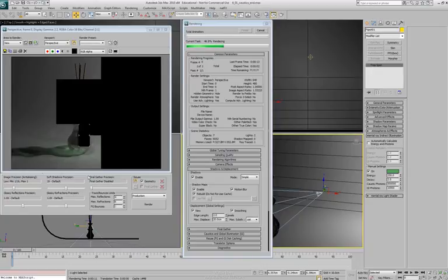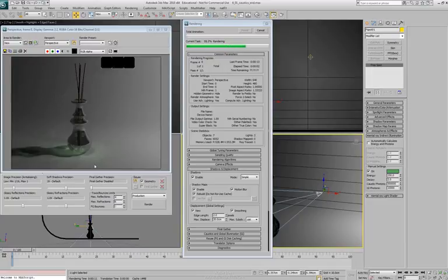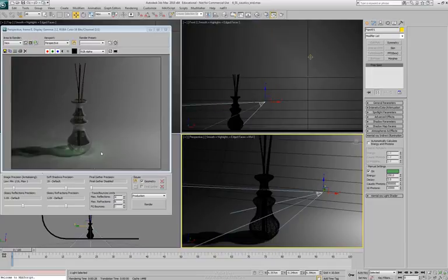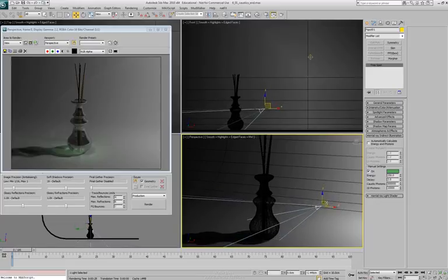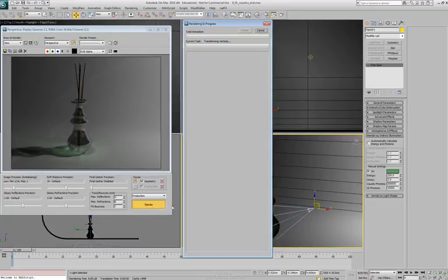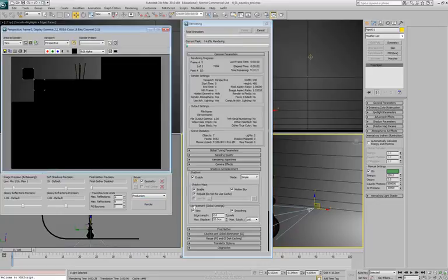And as it comes in the scene, we can see we've got some really nice crisp lines in here. We've got some nice little caustic effects going on. And overall, it's a good clean look to it. Now, depending on where the angle of our light is, it's going to change up a lot of how this actually affects. So let's say we were to actually adjust our light source some and pull it down and pull it a little bit closer to it. Now, when we do that, that's going to change up how that caustic effect is. So we'll take a quick re-render of it.